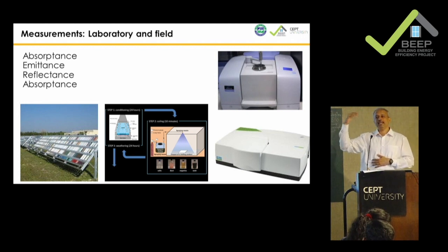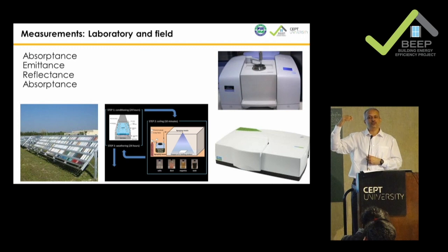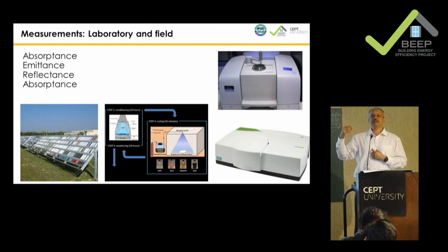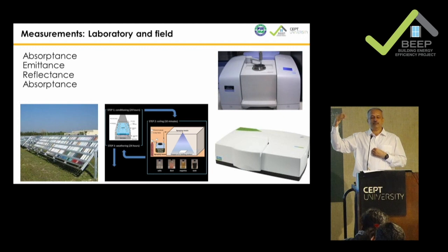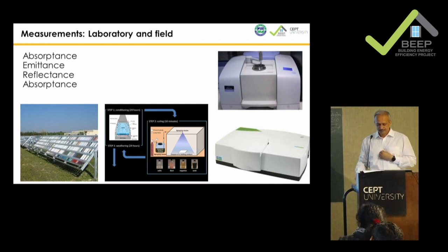The aging of a roof depends upon the surface and where it is. Probably in Delhi, something will age in 3 months, versus in places like Ahmedabad the same material might take about 2 years to age, because of differences in dust deposition, pollution, and so on and so forth, right?